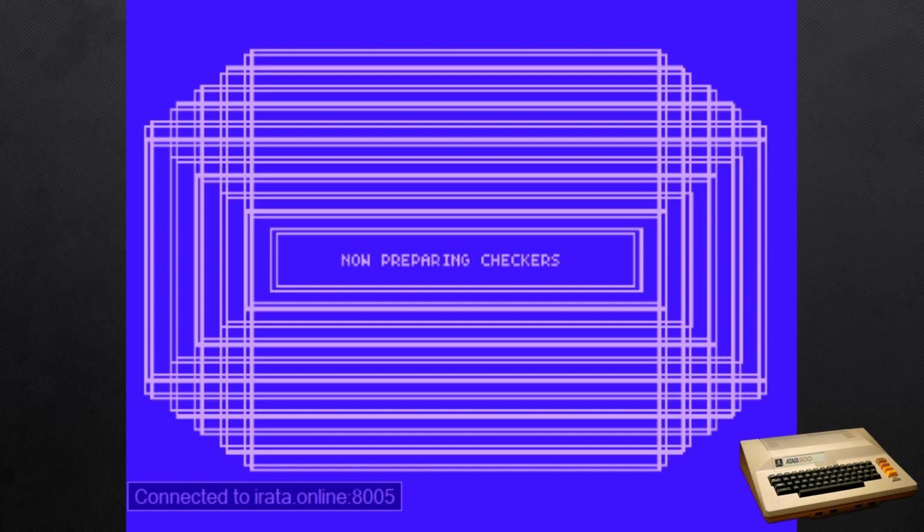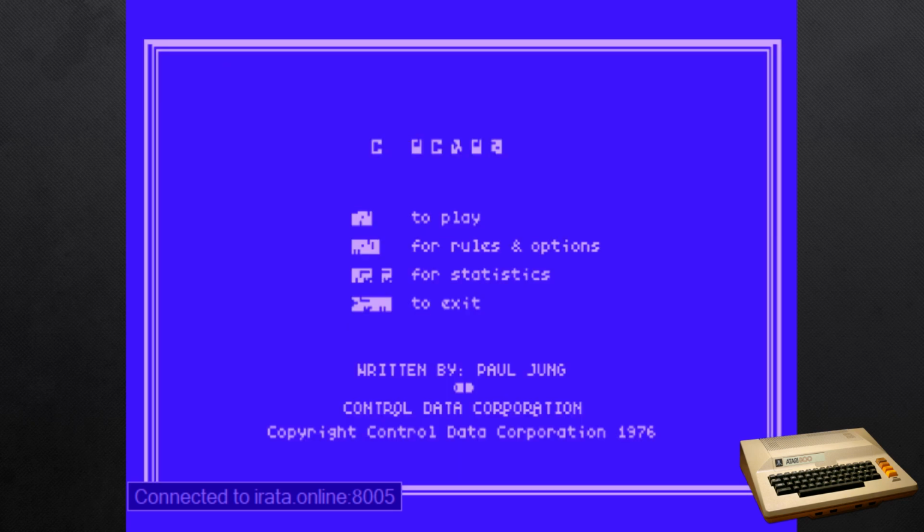and we'll be done in just a moment here. Now it is worth noting that there is no hardware flow control currently being implemented. This is why I'm running at 1200 bits per second. But I am trying to implement hardware flow control as best as I possibly can. And as we can see here, we still have some issues with characters not being decoded quite correctly.